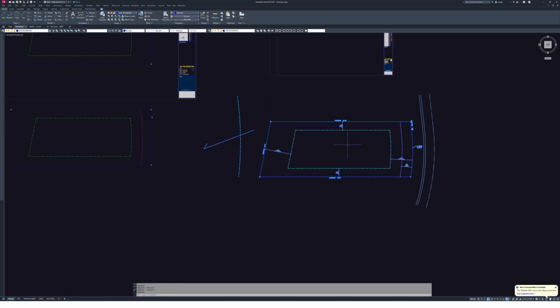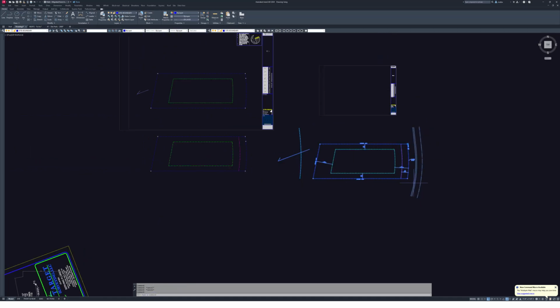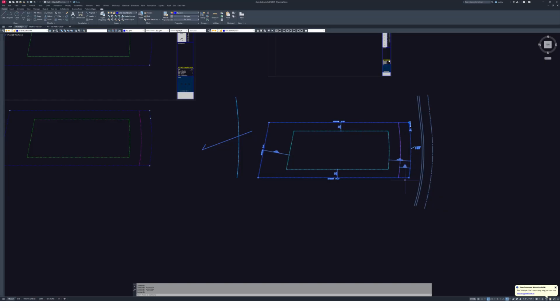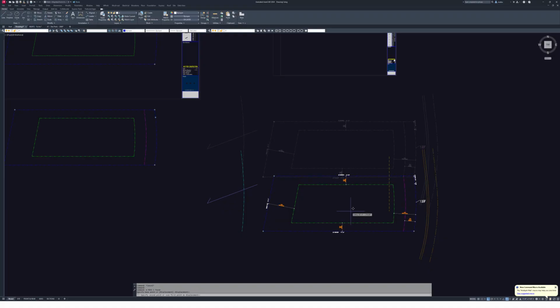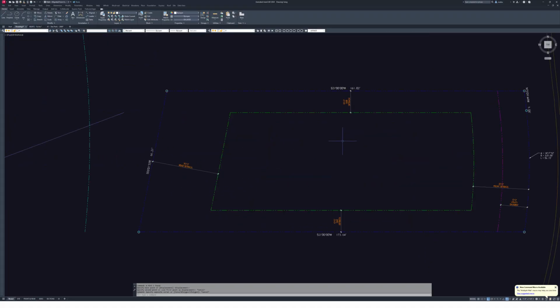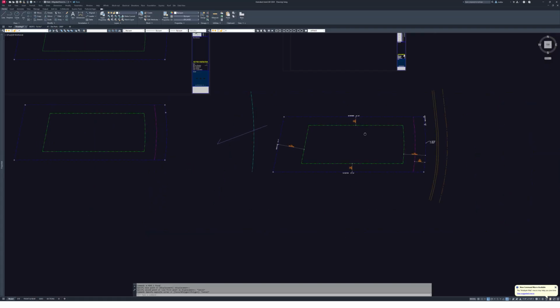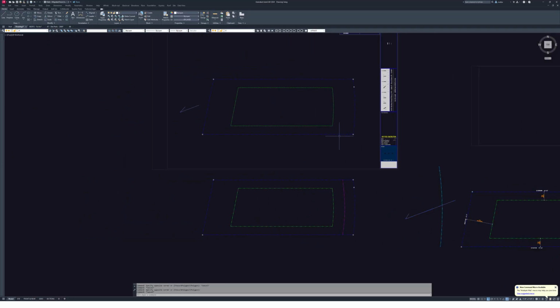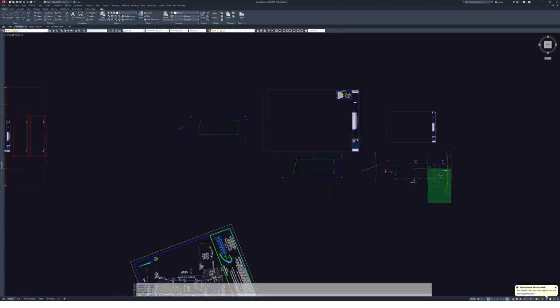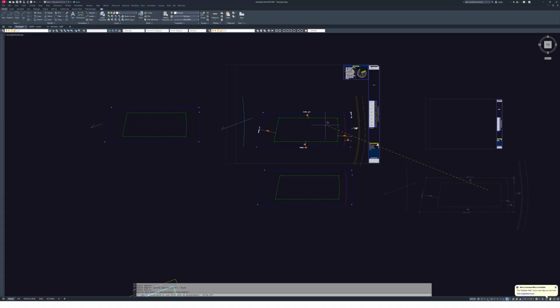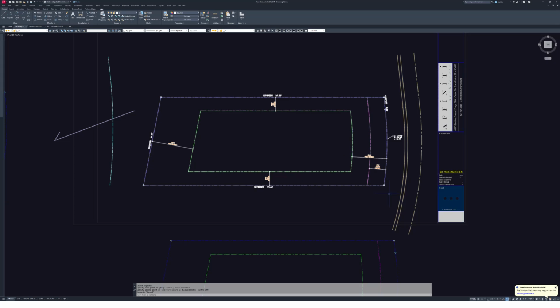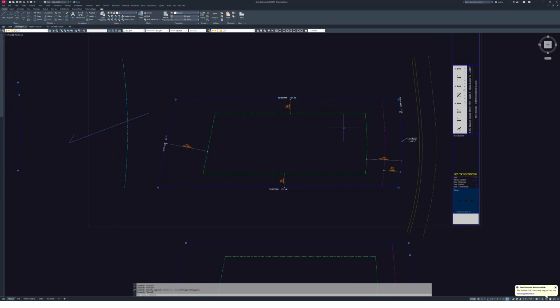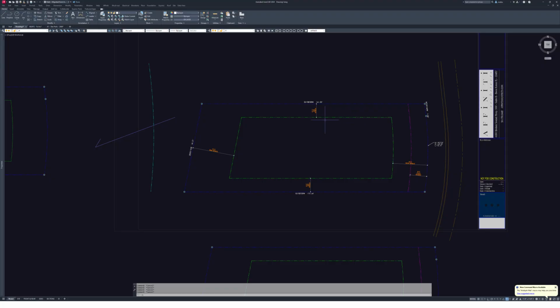So this is now a block, and I like doing it as a block versus drafting this stuff as loose geometry. This way, if I need to move the site, whatever, this stuff is all linked and relative to each other. This stuff should never be pulled apart. That's why I like working this way. We can move this guy out of the way and move this guy in, and this is now setting up our site plan.